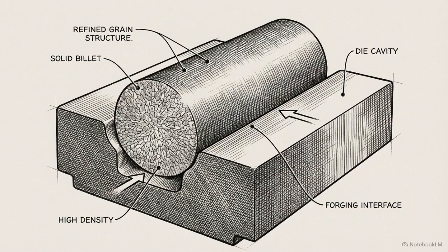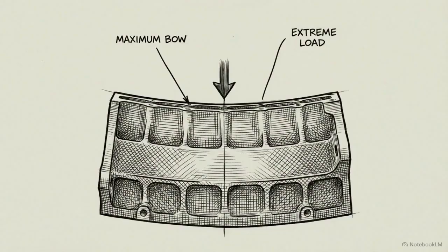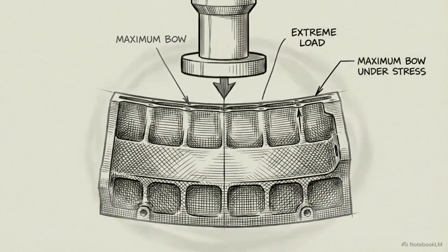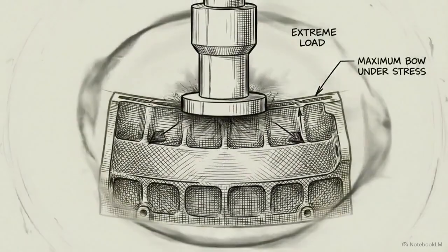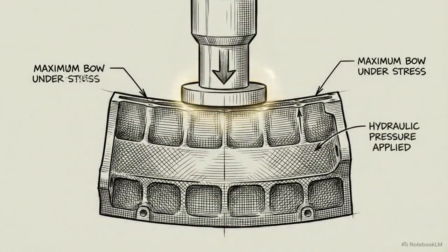Because of the aggressive cooling rates in HPDC, these alpha aluminum dendrites remain exceptionally small. This fine grain size mathematically boosts the overall strength of the part compared to slower methods like traditional gravity casting. The dendritic matrix forms a flexible, load-bearing skeleton. This ductility allows an engine block to slightly deform under thermal expansion rather than fracturing.